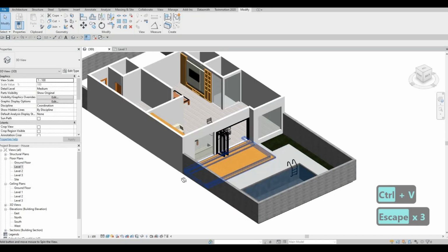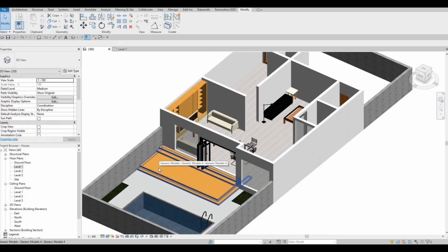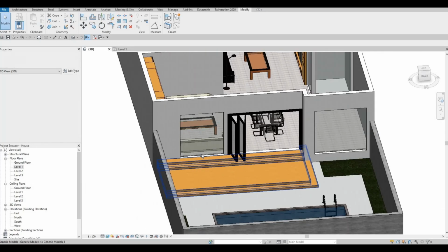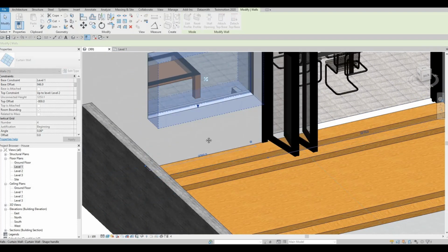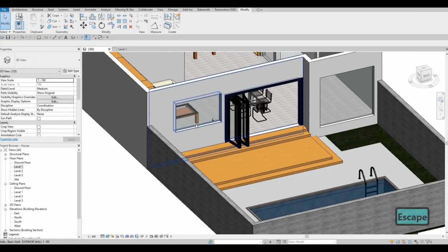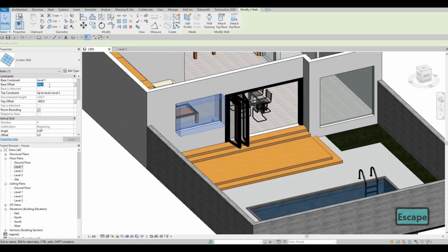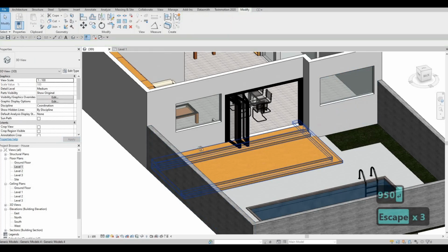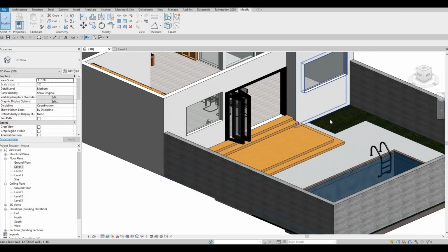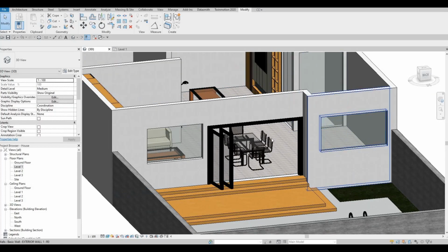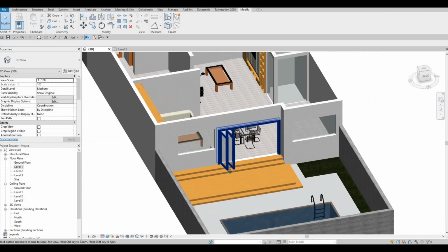and then we're gonna add a pergola so that once we add something here, it will really be nice. And then obviously we have to pull it up a little bit. So let's do this nicely. So make it 950 for base offset. There we go. And then at least everything is consistent with the height and everything else. And then here we're gonna add bushes and then a small tree that is at least visible with the kitchen that we're gonna create later on.